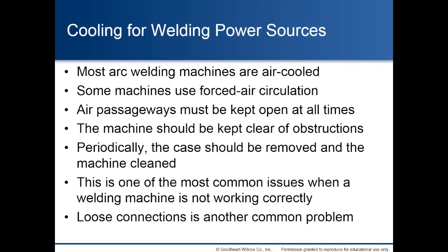Cooling for welding power sources. Most arc welding machines are air-cooled. Some machines use forced air circulation. Air passageways must be kept open at all times. The machine should be kept clear of obstructions. Periodically, the case should be removed and the machine cleaned. This is one of the most common issues when a welding machine is not working correctly. Loose connections is another common problem.